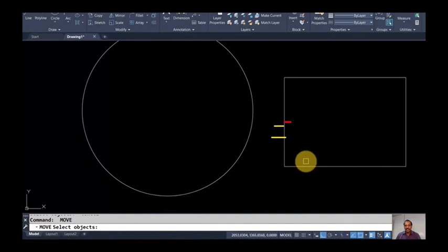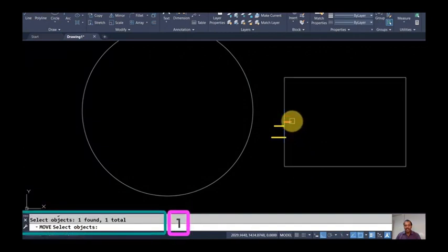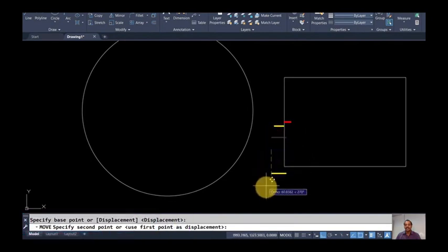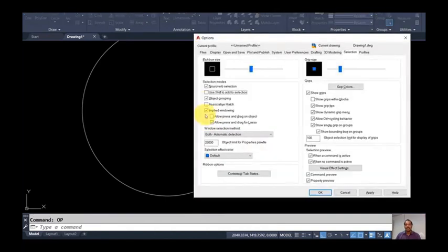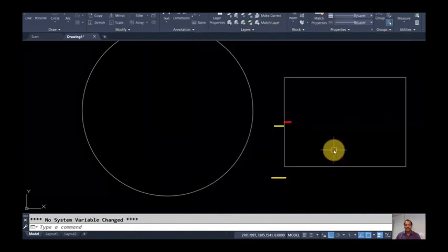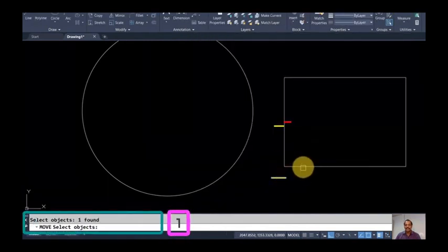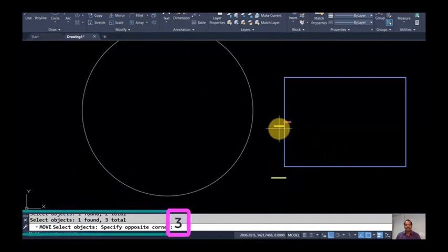See now, I'm going to do it again. I'm not pressing the shift key. What will happen? If you do not press the shift key, only the latest one will get selected and that will be moving. Okay. So for better performance of AutoCAD, it is better to use shift to add selections. Now, whatever you are selecting, all objects will get selected. You see here, I'm not pressing any shift button, so everything will be moving, right?